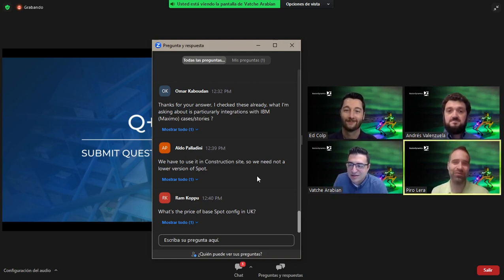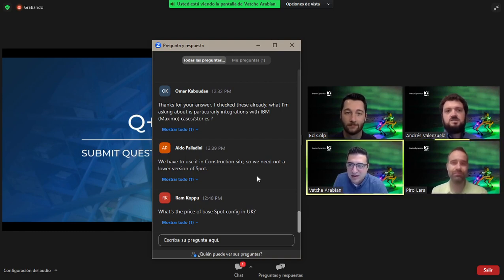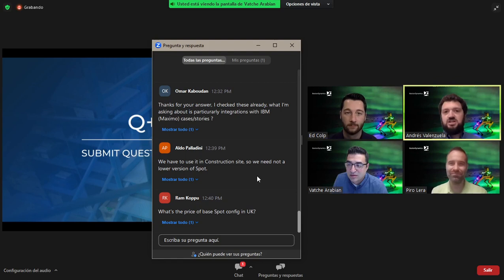Yeah, so if the environments are very, very similar to each other, and let's say you put the fiducials at the same exact spots, and you try to make it as identical as possible between the two environments, you might have some success. But as Andres mentioned, it's designed so that you record a mission in one area and then you can easily play it back in that area. That being said, it was designed to be robust to smaller changes in the setup in that area. So we have robots that run missions around the office here, and pallets get left in the hall, and they still navigate fine around those. But an entirely different location might be hard.